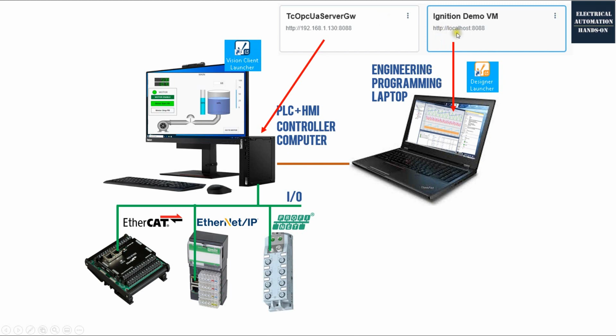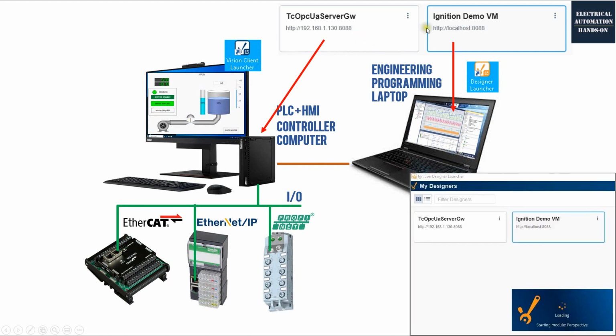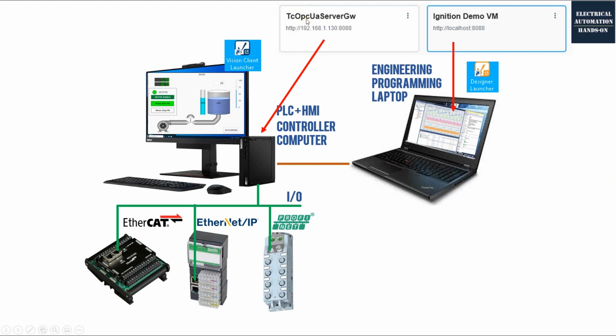And then when you go on site, you can open the remote HMI server. That's the on-site HMI server. And open your local project and this HMI server project at the same time. And open the HMI screens you prepared. And copy those HMI screens and the variables from your local HMI project to the remote HMI server project.